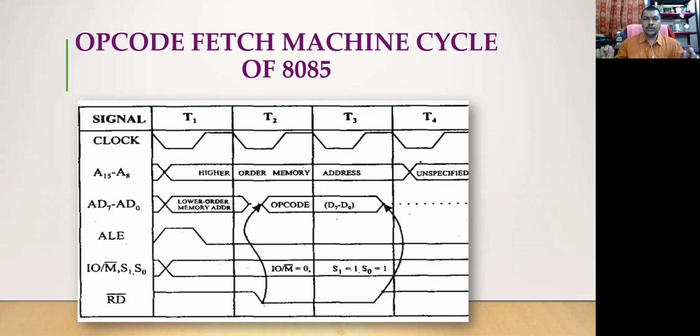What I am trying to tell you here is that the opcode 3E, written in memory location 600, is being fetched from that memory location to the microprocessor and the instruction register, to decode it, execute it and generate certain control signals for execution. The time required to fetch that opcode from 600 to the instruction register for decoding is called a machine cycle.